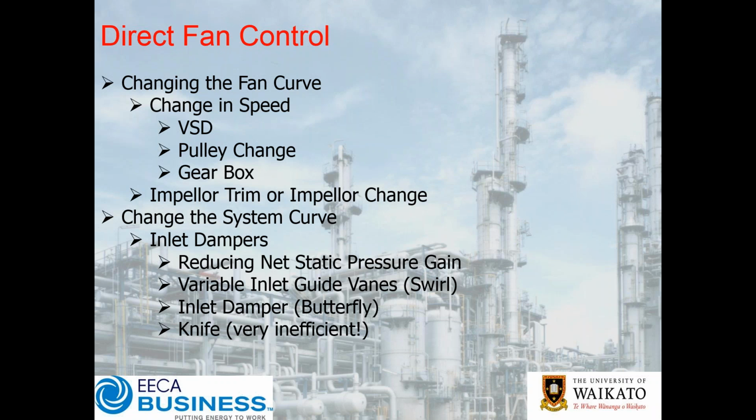But fundamentally, when we're talking about direct fan control, we're either directly changing the fan curve itself, or indirectly by throttling the fan, either before or after the fan, the effective output of the fan. But it's really about controlling or adjusting the fan as opposed to the rest of the system.